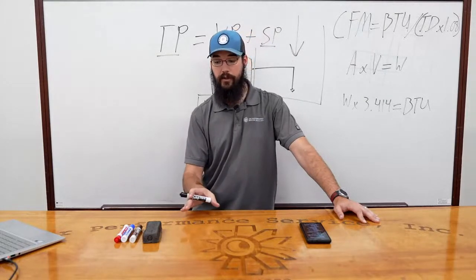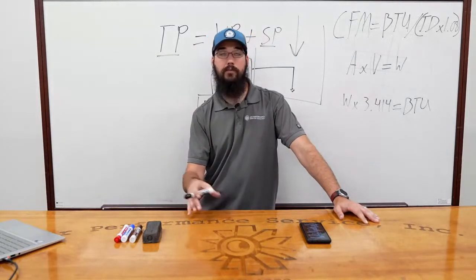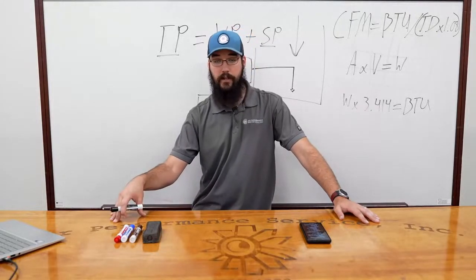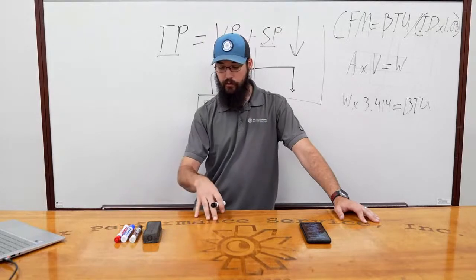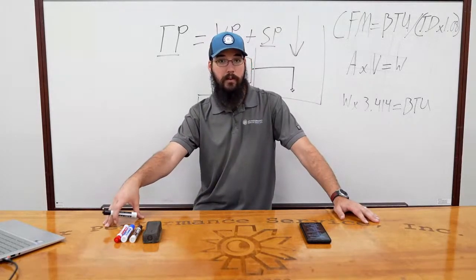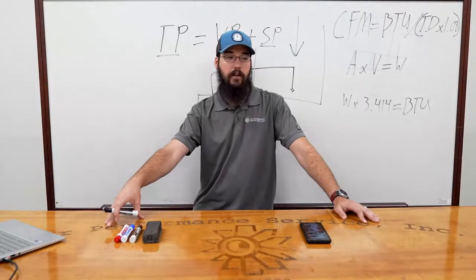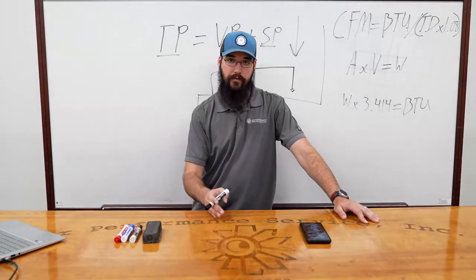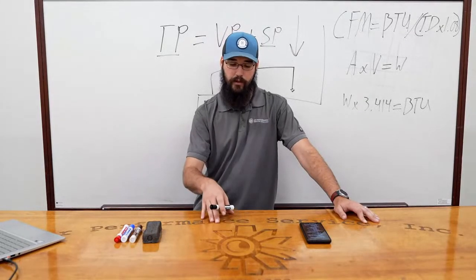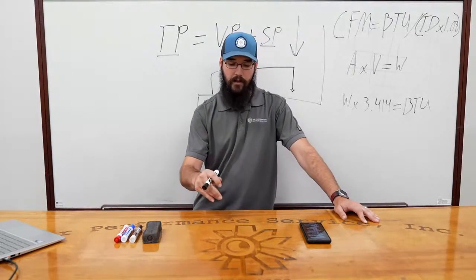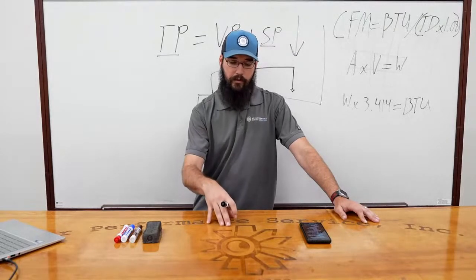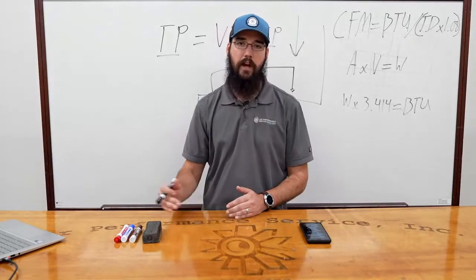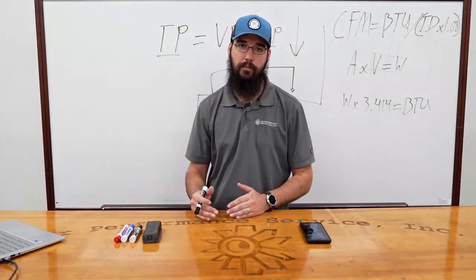As an example of this, you may be running mid to upper 40s on your saturation, but your superheat may be pushing 20 plus, which for me, that's a bad thing. Because of your airflow, it would be easy to overlook the saturation and just see high superheat and say, okay, I want to get that superheat down.